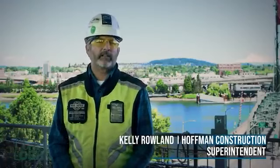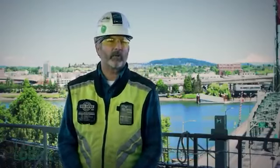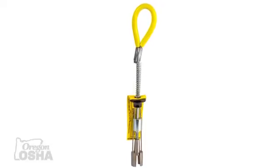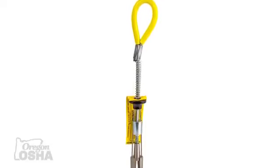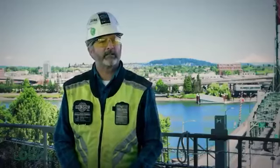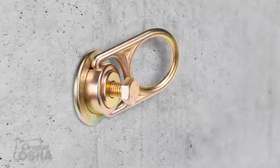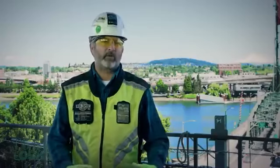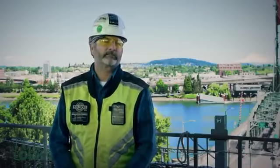The most popular type of anchor is either going to be a mechanical one, like a wedge anchor, where you drill a hole and then there's a mechanical way for that to tighten up. It has engineering behind it. My favorite is cast-in anchors. Not only do you have the anchor and the pull-out of the threads of the bolt that you're using, but you have all the concrete there as well.